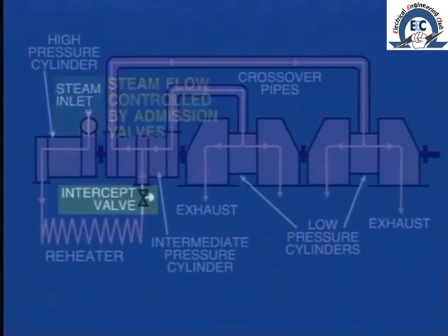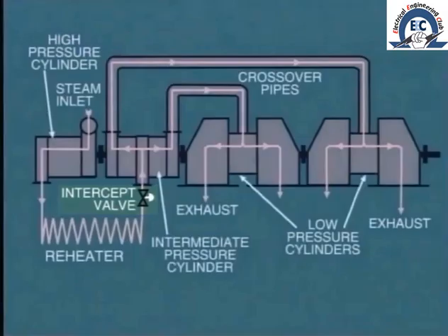However, note that with reheat units, additional control valves, known as intercept valves, are fitted at the inlet to the intermediate pressure cylinder for protection purposes. We'll be discussing this in detail when we look at control and protection in the next module in this series.